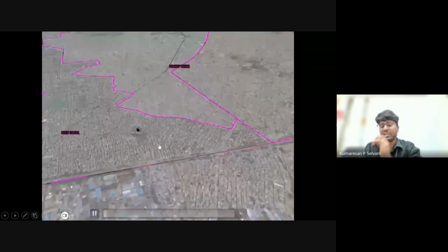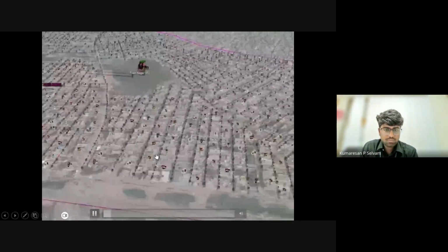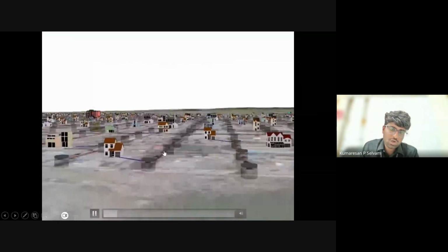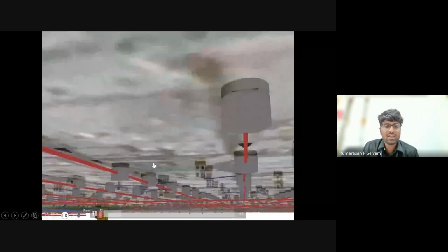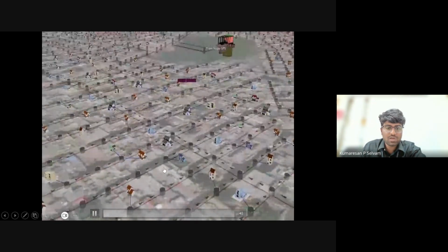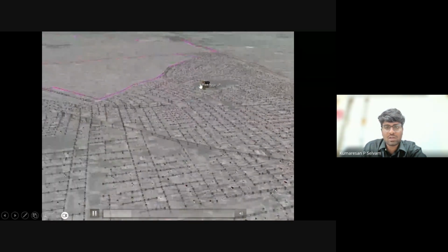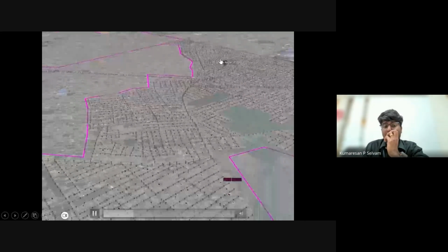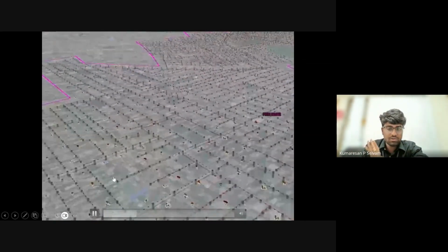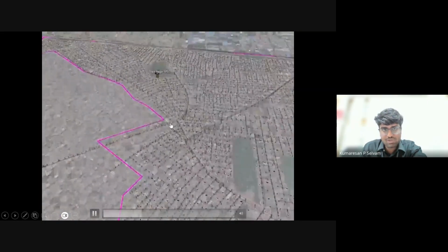And this is a sewage treatment project where you can see the pipeline, how it is crossing, and at what depth the manholes should be buried and placed. Even that you can visualize. These are all sewage collection pipes, and it is taken to the pump house. This is the pump house, from which it is taken to the treatment plant. This is the treatment plant, and the sewage water is treated there. And this is a network of sewage collection.